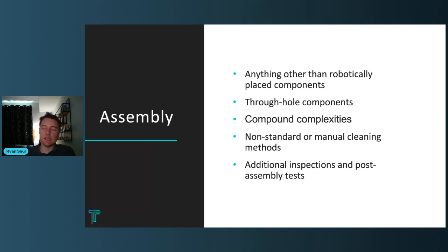Another common example we see is boards that have very, very fine pitch SMT elements or thermally sensitive SMT elements. No problem. These days, fine pitch elements are easy on the assembly side for modern manufacturing equipment and processes. But they also include heavy magnetic or mechanical solder joints with high thermal mass on their board. And this is challenging because now you have to design a reflow profile that will successfully reflow these large mechanical or thermal solder joints without damaging these very sensitive components.